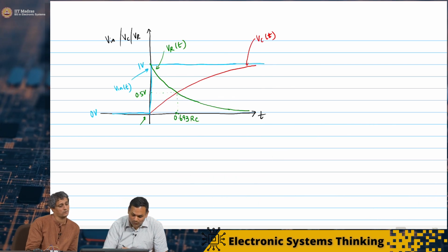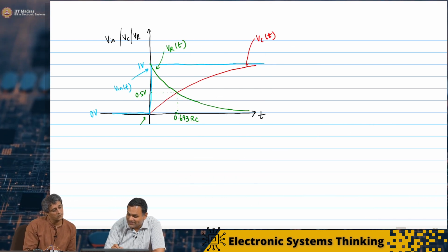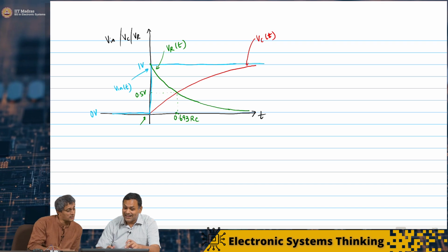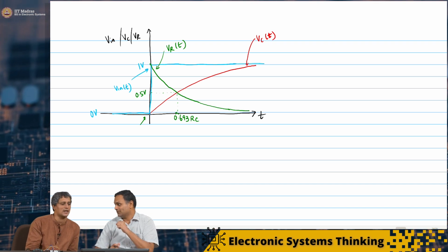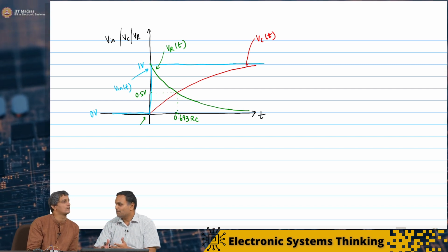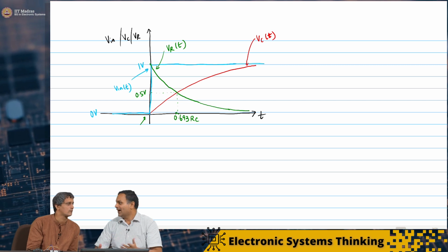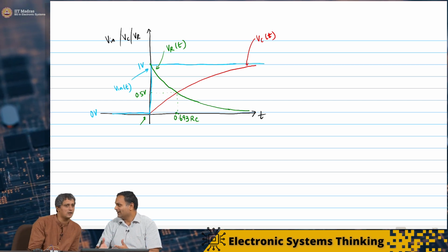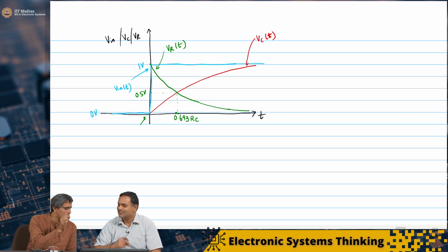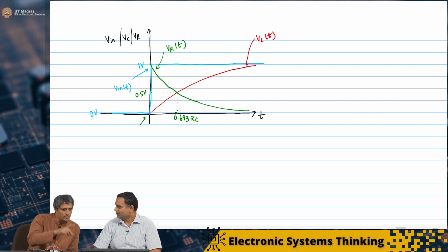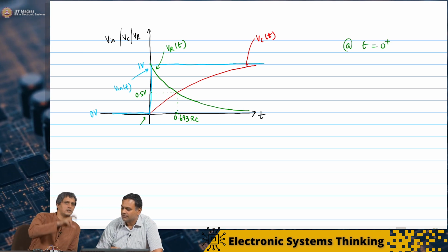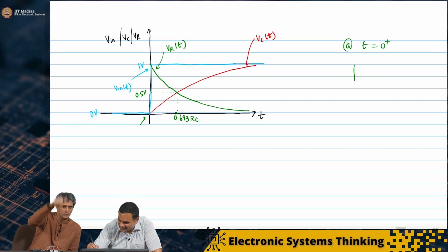Right? And what is happening? The voltage across the resistor is actually seeing a sudden jump, exactly like the input. Exactly. And because the capacitor is discharged, you look at it as a short circuit. You will almost get 1 over R, so input voltage divided by R as the current flowing through the resistor. Okay. So just for a small time after 0, right? That's correct. So effectively the capacitor has just pulled it to ground. It's like a short circuit to ground, and you have a DC supply of 1 volt, with the resistor going to ground.